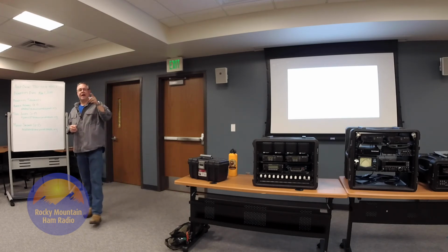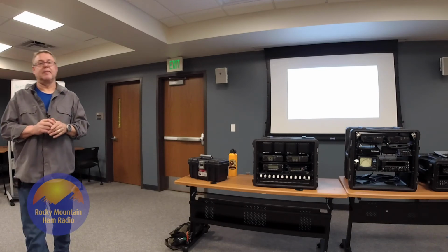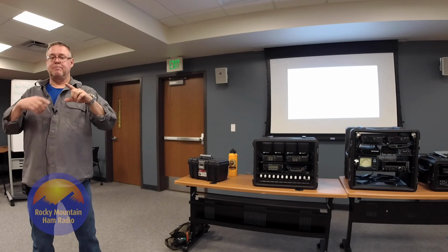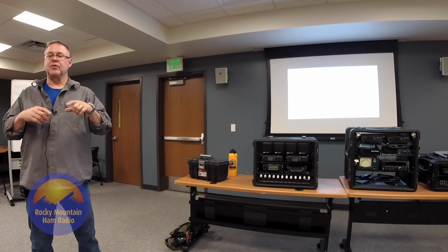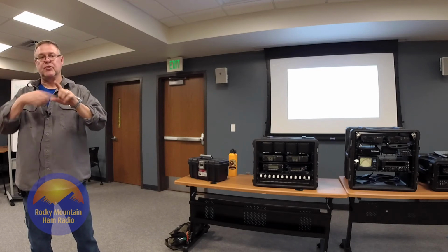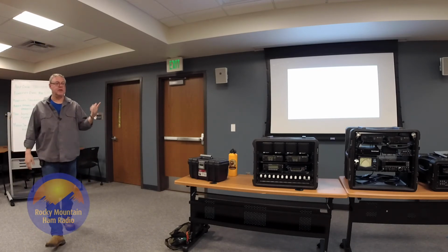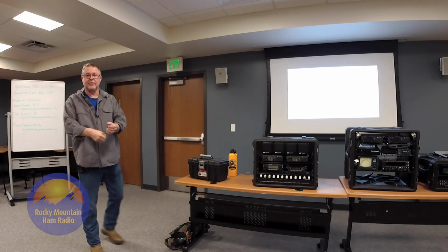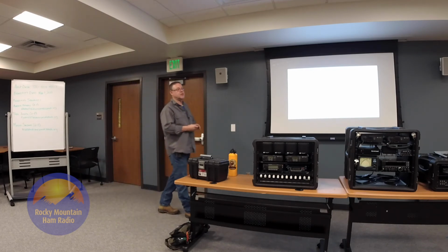That's a good point. I've seen documents about people that carry the big toroid, and they build themselves a short jumper extension cord. They cut a piece off and wrap it through the toroid and put the appropriate cord caps on each end, and they carry it in their cold box. And if there's a generator running, they plug it in first, and then they plug the real extension cord. That's a good point. There's guys that do that.